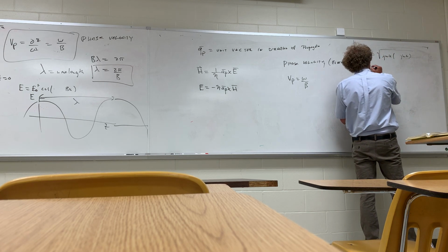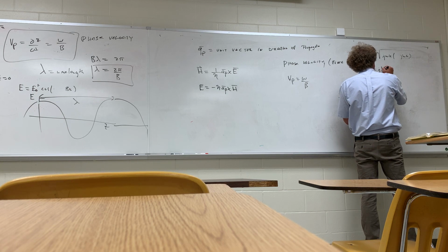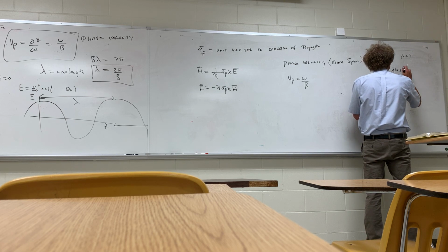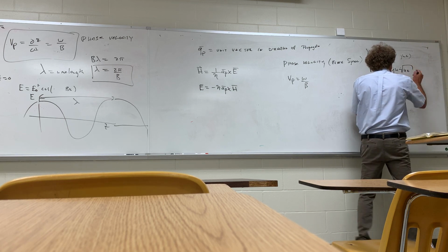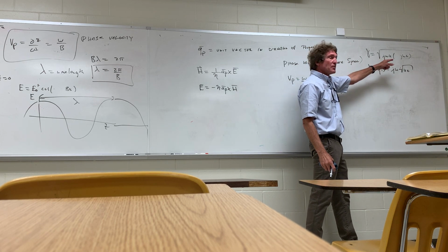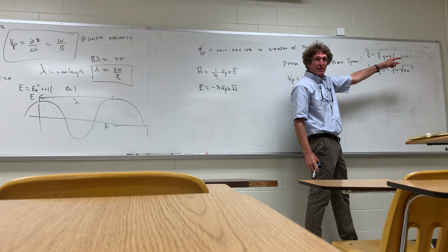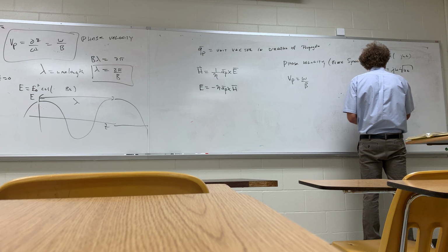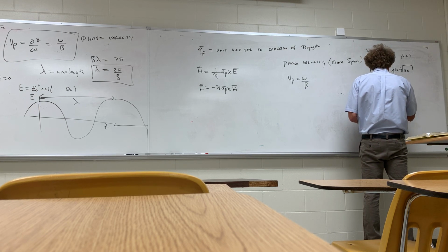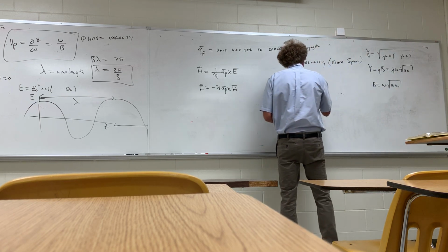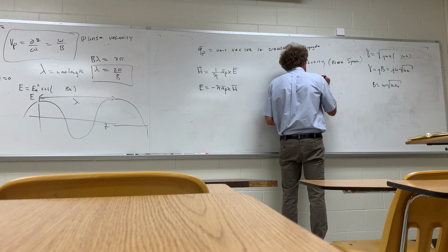Now when you look at this, you have gamma simply equal to j beta, sigma 0, equal to j omega times the square root of mu epsilon. Do y'all follow me on that? Because you've got 2 j omegas on the square root side, so you bring out a j omega, then you have the square root of mu times epsilon. Can you all see it over there? Yeah. All right. That means beta is equal to omega times square root, and now we're assuming free space, so it's mu naught epsilon naught. So now I come back over here and I find the phase velocity in free space is omega over beta.